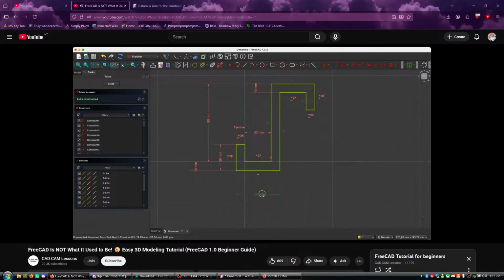And so I will delete this dimension here. I select this dimension, press delete, and we will define the distance between these points as 10 millimeters. Okay, and now I change this dimension. I enter 40 and everything works. As you can see, even though a problem occurred, we can solve it very quickly and easily.